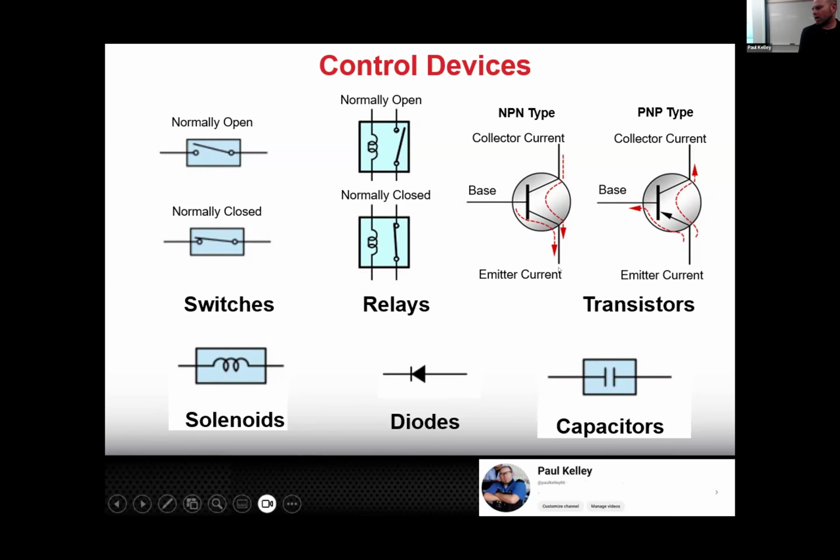So if the power source is inside the ECM and then coming out of the ECM, we should have this, and that should power the fuel pump. I go to the ECM and I'd say like, hey, are you giving me the power that the fuel pump needs? Yes or no? And if I probe right here and it's supposed to be giving me, let's say, 12 volts right here, if I don't have 12 volts right here, I'm suspecting maybe this transistor is no good.